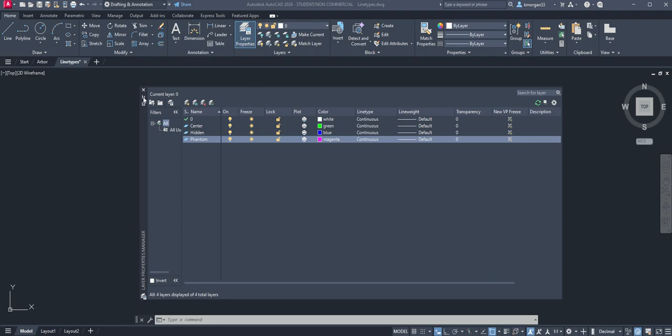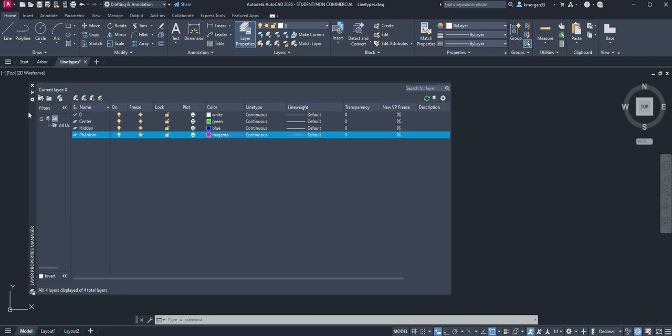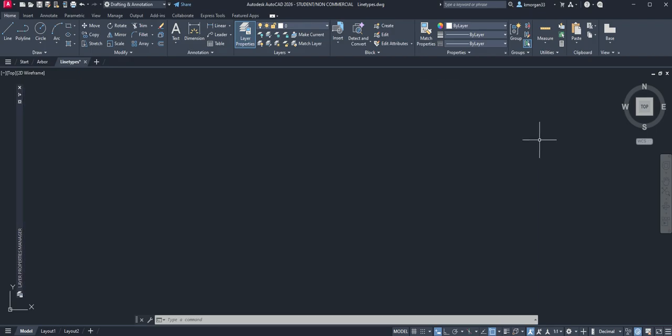And then go ahead and hide this, move it over there. We are going to now go to home tab, and then of course we are going to draw 3 horizontal lines. You can do the F8. So click on the F8 here, and then just go ahead and draw 3 units far away.